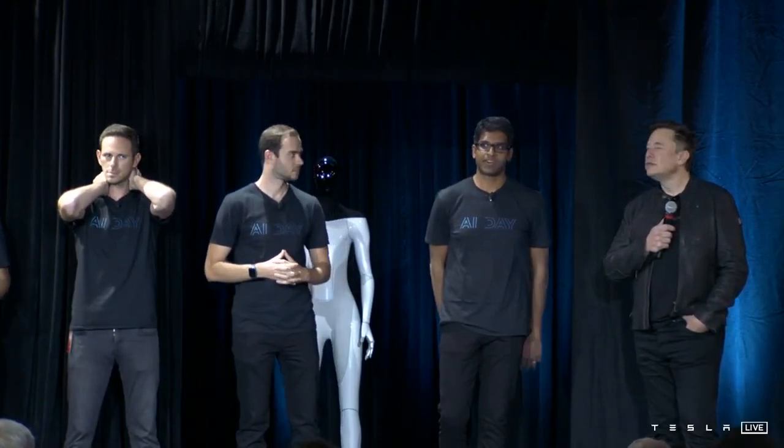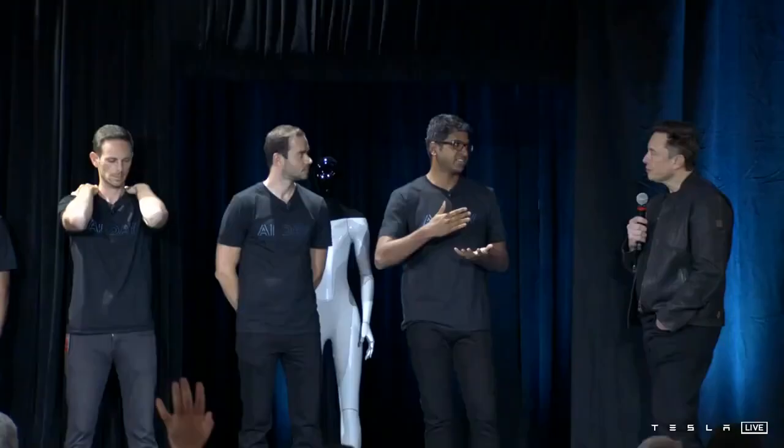With different kinds of modalities to bring down that error. We primarily try to find scalable ways to label. On some occasions, we use other sensors to help benchmark, but we primarily try to use cameras for this system. Okay, thanks. Yeah, I think we want to aim for the car to be positioned accurately to the centimeter level, something on that order. Obviously, it will depend on distance. Close by things can be much more accurate than farther away things, and they would matter less because the car doesn't have to make decisions much farther away. And as it comes close, it will become more and more accurate. Exactly.